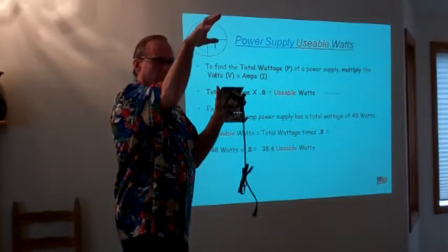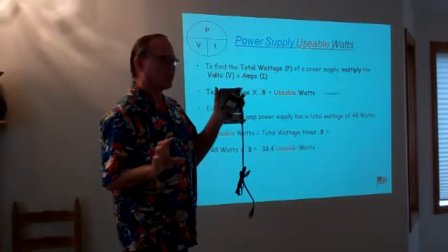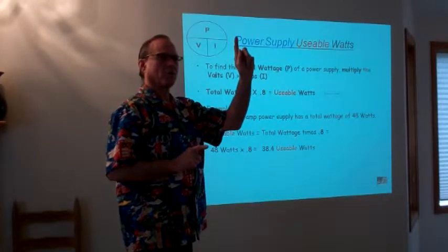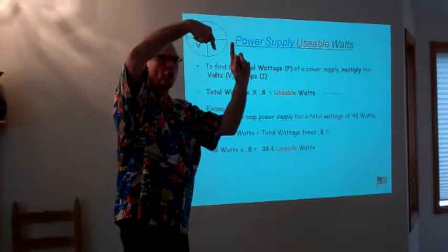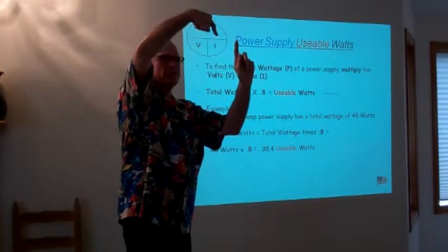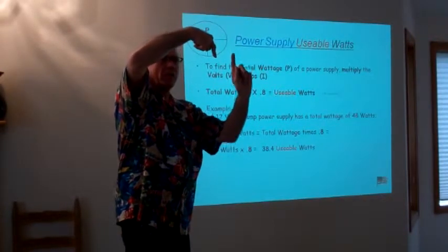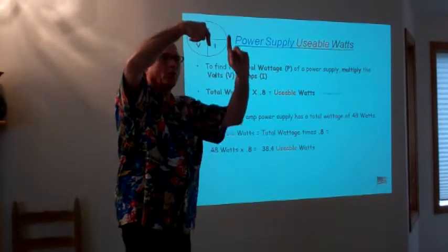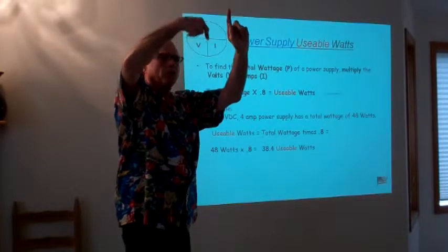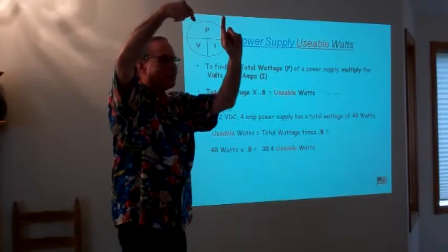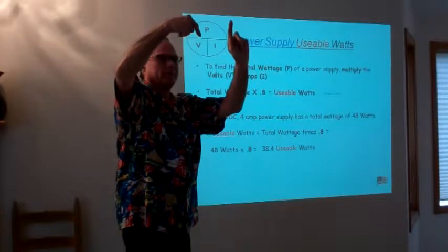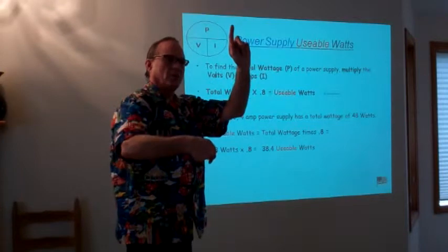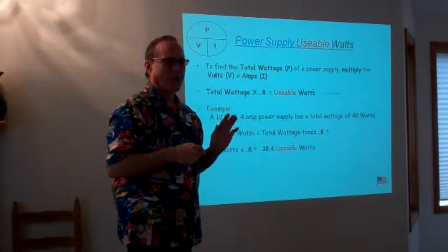We have a positive side, if you will, and another side, which we call the negative side. It's not really that way. What actually happens in that case is we have a direction of current flowing this way, and then when it turns on to the other side, it goes the opposite way. So you have flow this way, then flow this way. So if we put our diodes 180 degrees apart, we only allow flow to go through on this side, but normally if we didn't have this other diode, we would not have this side of our cycle. So by putting our diode in that direction, we then are able to get this flow. So that gives us what we call full wave rectification.